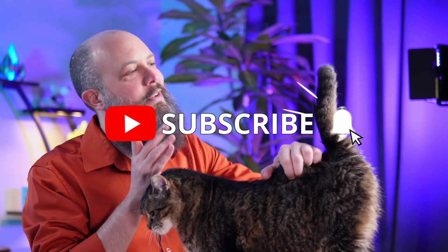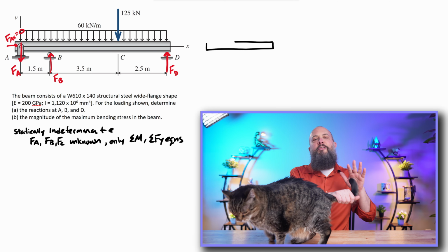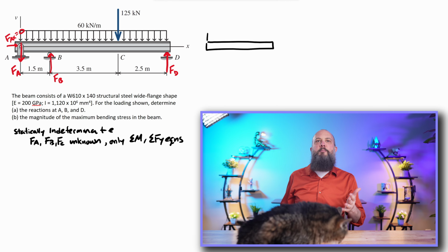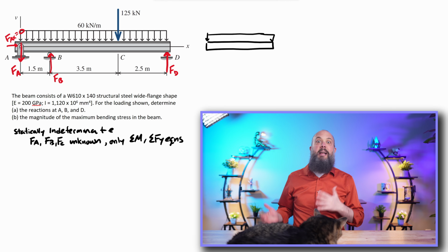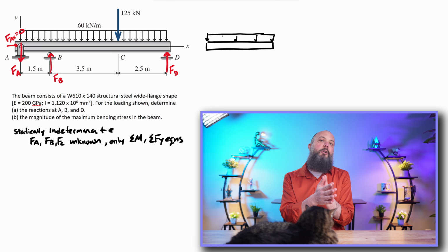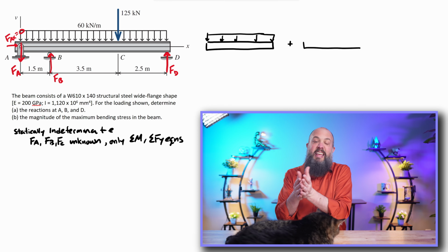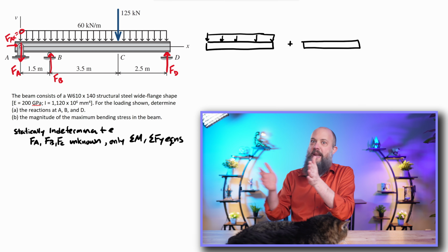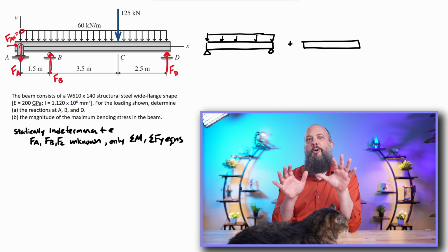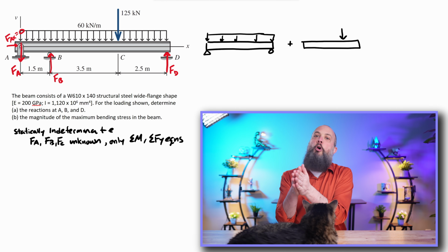So your TA Serenity loves superposition tables. Your first thought is, is this beam most similar to a cantilever beam or a simply supported beam? Because that's going to choose which tables you get to use. For us, this is most like a simply supported beam with an extra piece in the middle. So first, we're going to ignore that roller joint in the middle.